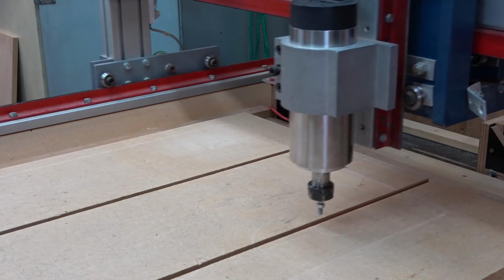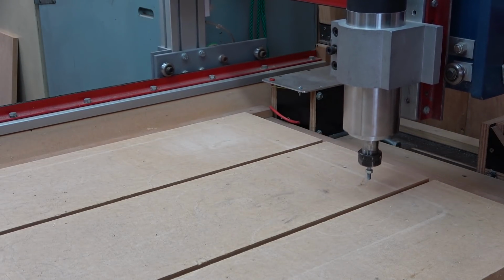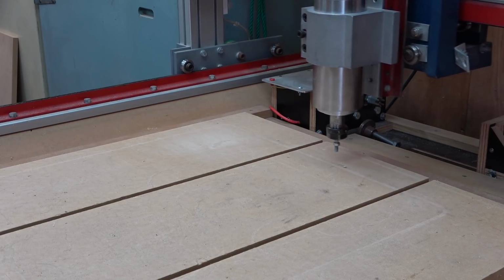I then increased the acceleration by 3 times, and I increased the constant velocity tolerance by a massive 180 units. It still will not run smoothly around that oval, even though I know for a fact it's well within the capabilities of the machine to do that.